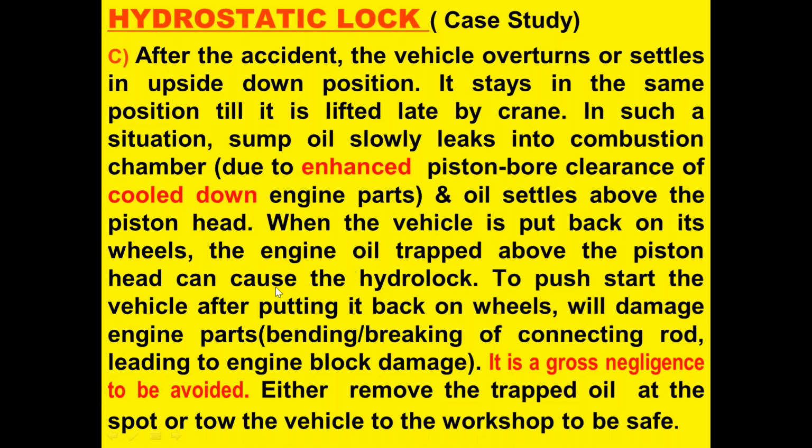When the vehicle is put back on the wheels, the engine oil trapped above the piston head can cause hydrolock. To push the vehicle after putting it back on the wheels will damage engine parts, bending or breaking the connecting rod, leading to engine block damage. It is gross negligence to be avoided. Either remove the trapped oil at the spot or tow the vehicle to the workshop to be on the safe side.